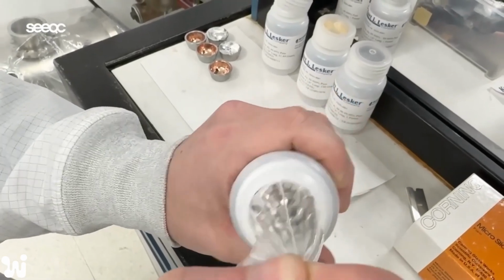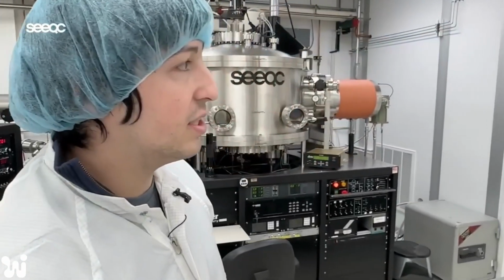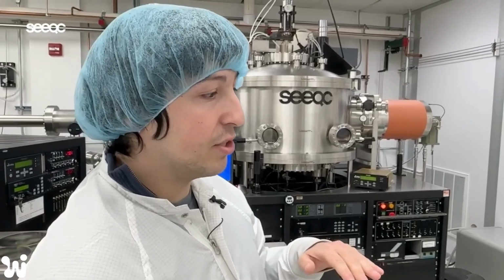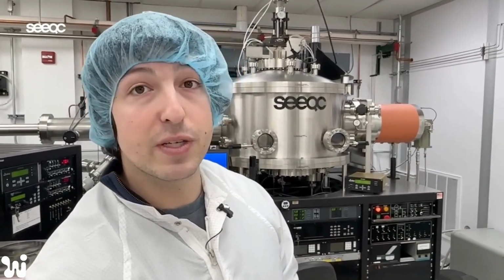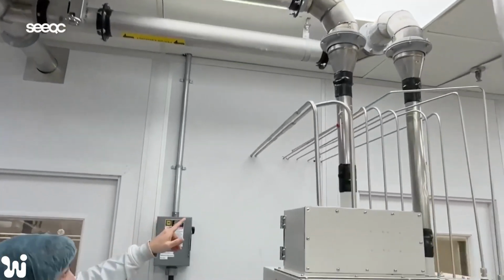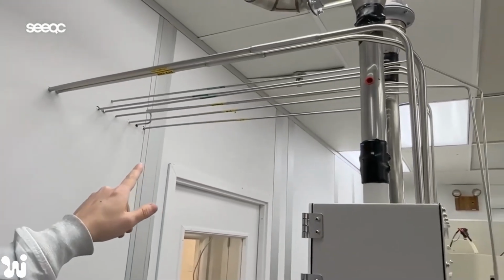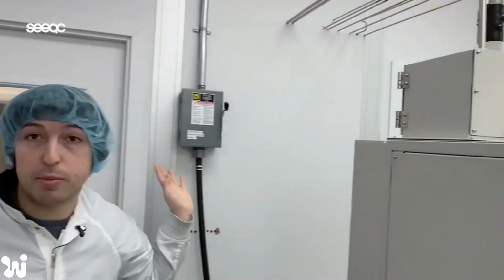This is a PECVD tool we use to deposit silicon nitride. That is used as an insulator to protect your resistors and your wires from interfering with each other. It also has an added benefit of being clear, so you can see through it to see all of your features underneath. We have lines here for our gases that come in: silane, ammonia, argon, nitrogen, and hydrogen go into the tool, and these are the exhausts that go out, which are then sent to a scrubber that cleans them before they're released to the atmosphere.